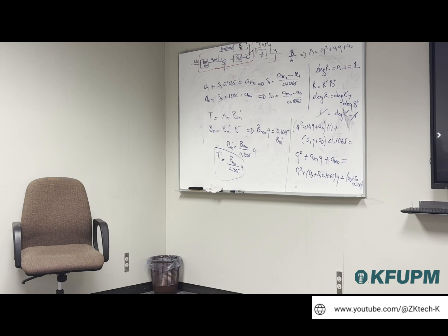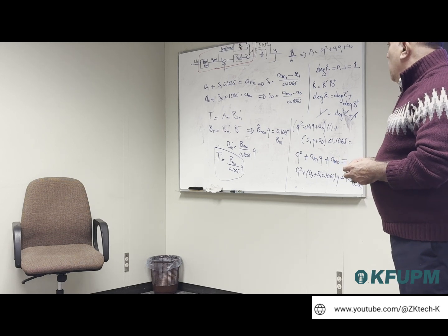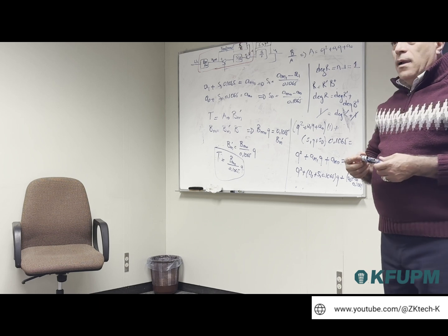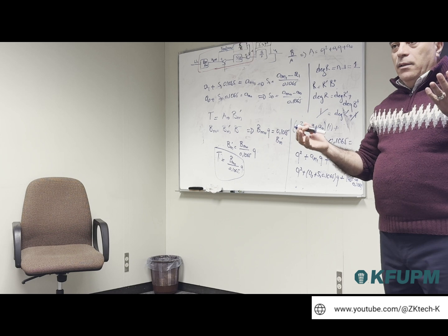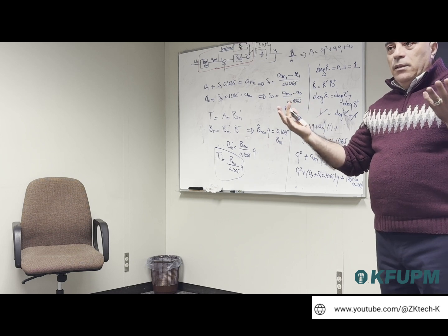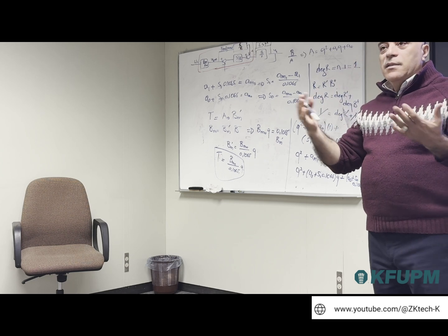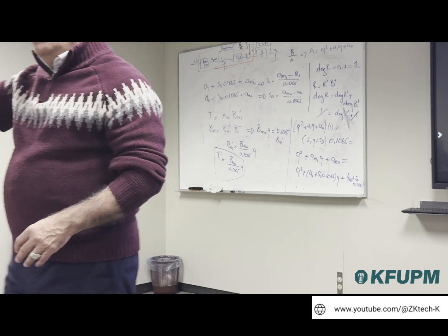Does this method ensure a stable R? Because we have a stable R. It is a stable R. It's going to be a stable R. In general, it has to be stable R because you have your reference model and you are not inversing the unstable zeros. So unstable zeros, we are not including them in R.